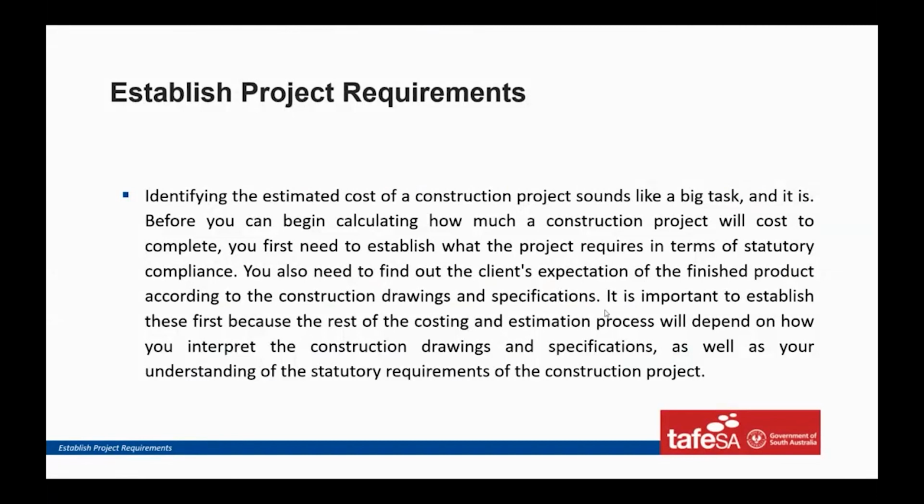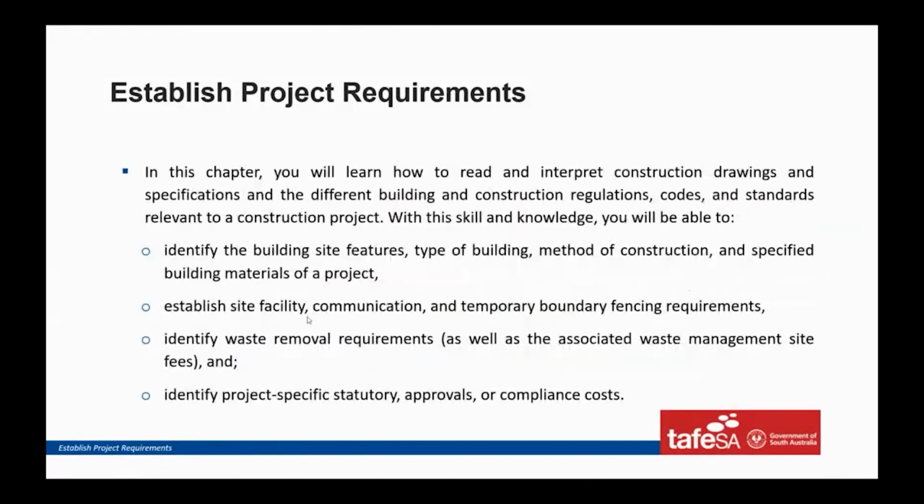If we don't get this right and then we start to actually work the job out, we're going to be in big problems. And so that's another thing. So understanding the statutory requirements, and that's the reason that you had that assessment. And so this is where some of these little bits and pieces will be quite handy. There's the dot points: identify building site, identify site facilities, identify waste removal requirements, as well as the associated waste management site fees. This is expensive business nowadays.